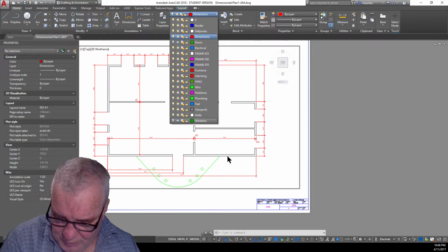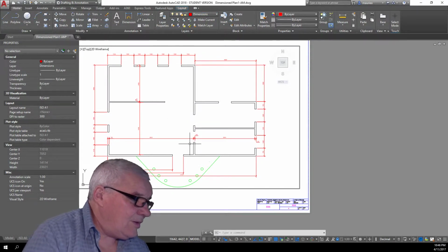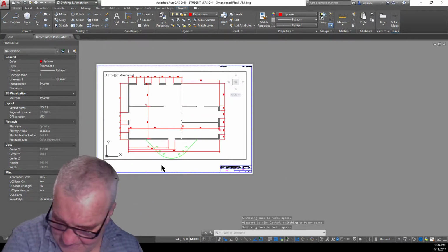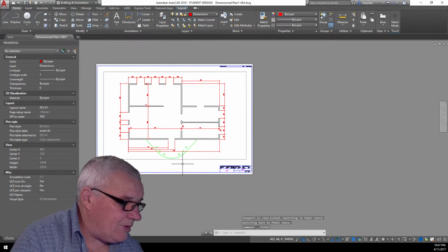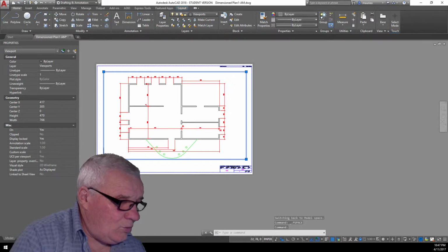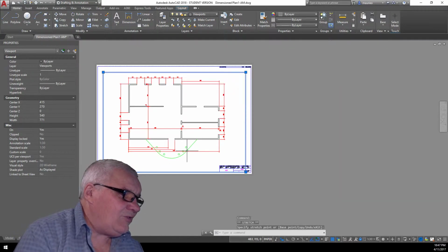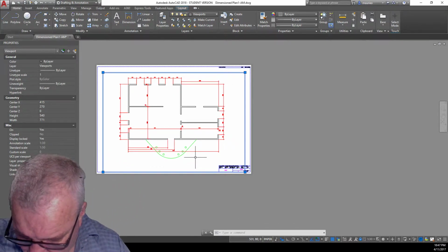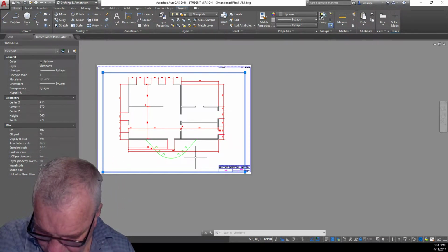Okay, modify the viewport to display the entire entrance portico. Modify the viewport. Is that what they're saying? So that means going to paper space, selecting the viewport, and we'll bring it perhaps down there. So that displays the entire portico, with a bit of room around it.